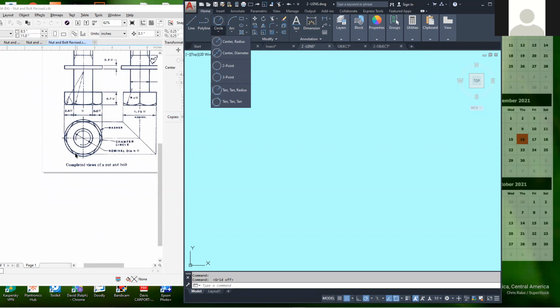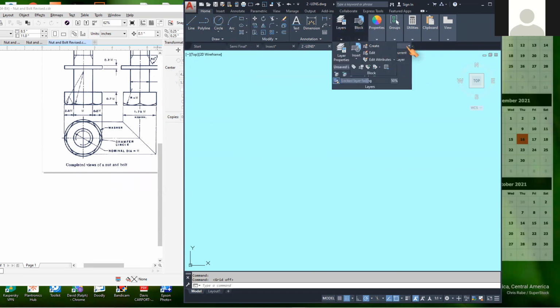You could draw a circle twice M and put the hexagon inside. So let's say we have M10, the diameter would be 20. So you could draw your circle 20 and put the hexagon on the inside of that. But we are using AutoCAD, so what we can do is draw a polygon. First of all, let me get the center lines.